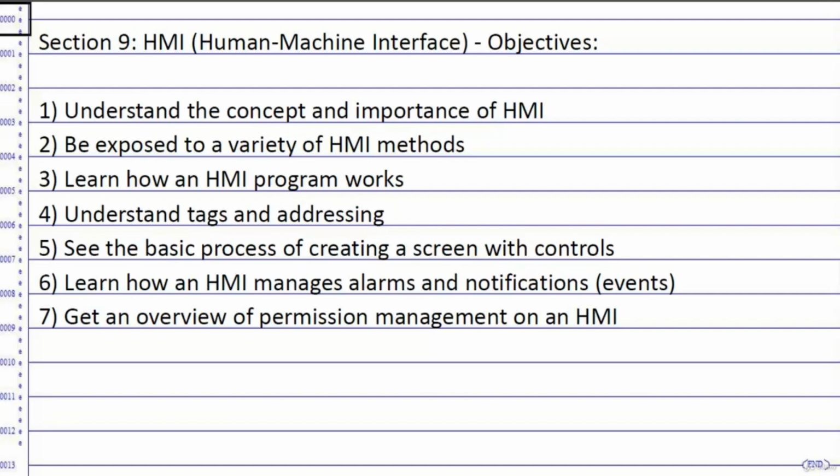It's time consuming, and you'll want to experiment with the different controls available in your HMI. But you have multi-state indicators, push buttons, numeric displays, text displays, numeric entries, and these are things that you see across the board on almost all development environments. You have little lights and bulbs and meters and things like that. The animations are a lot of fun to play with, and different environments have different animations and visibility effects, and they all tie back to tags in the PLC.